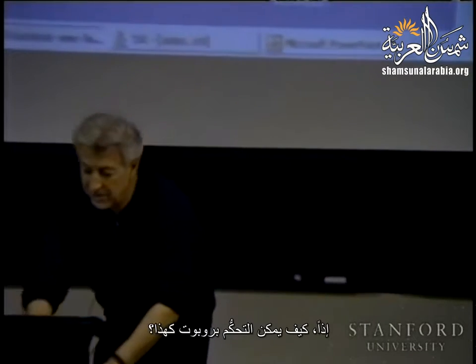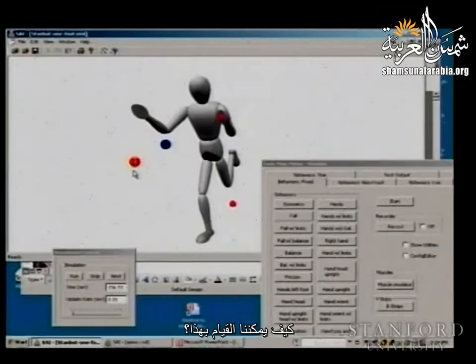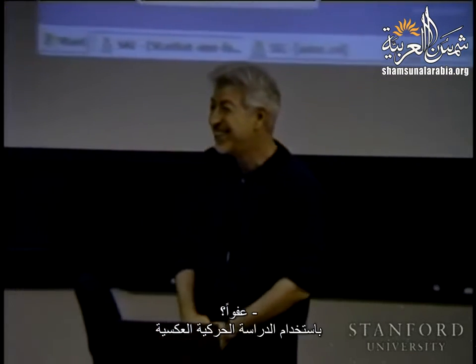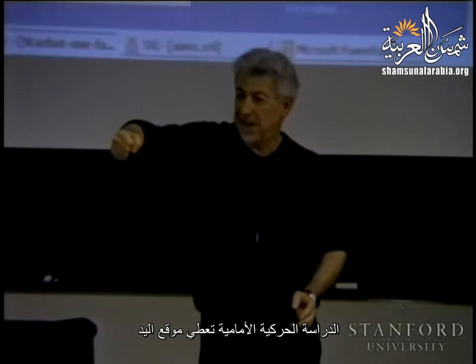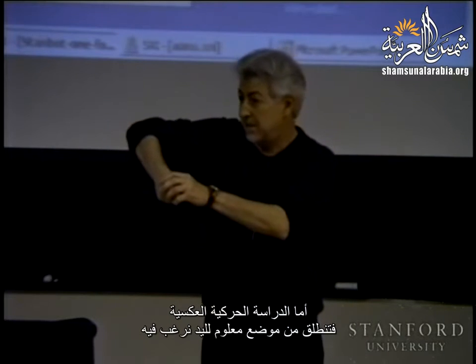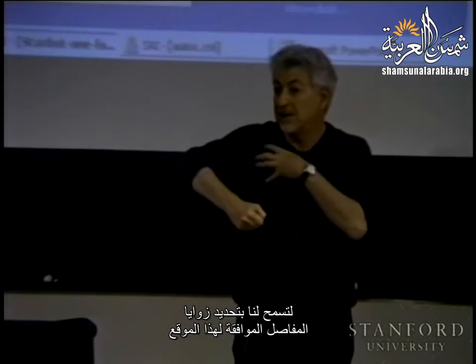So how do we control a robot like this? So let's say I would like to move this to here. How can we do that? The hand, I would like to move it to this location. I'm sorry? Forward or inverse kinematics? Oh, very good. Well, the forward kinematics gives you the location of the hand. The inverse kinematics gives you, given a position for the hand that you desire, the ability to solve for what joint angles you have.